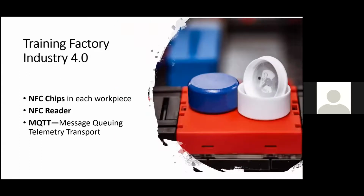The use of NFC chips in each individual workpiece, each of which has a unique identification number, enables the positions of each workpiece in the work cycle to be mapped. And the use of MQTT, message queuing telemetry transport, allows the network TXT controllers to communicate with one another.